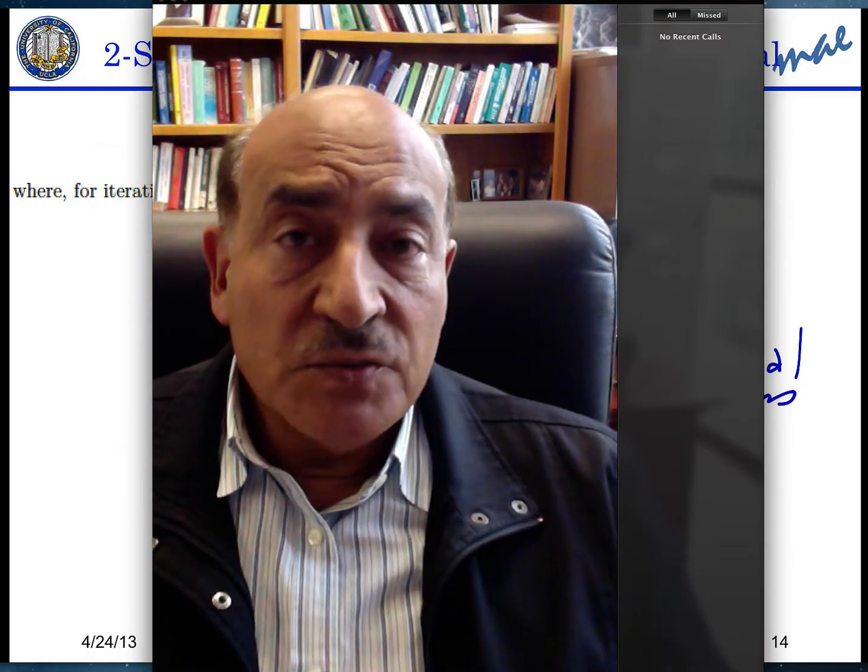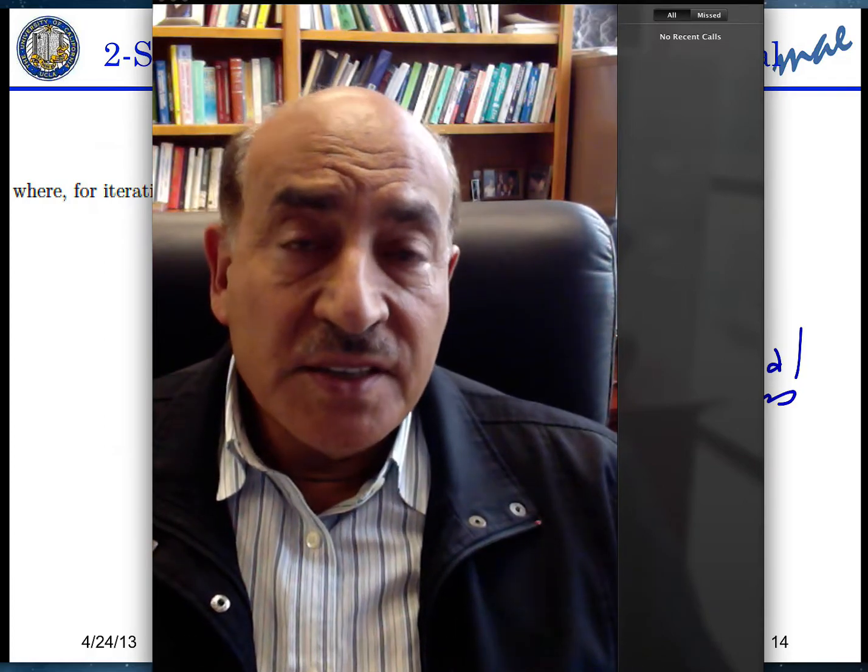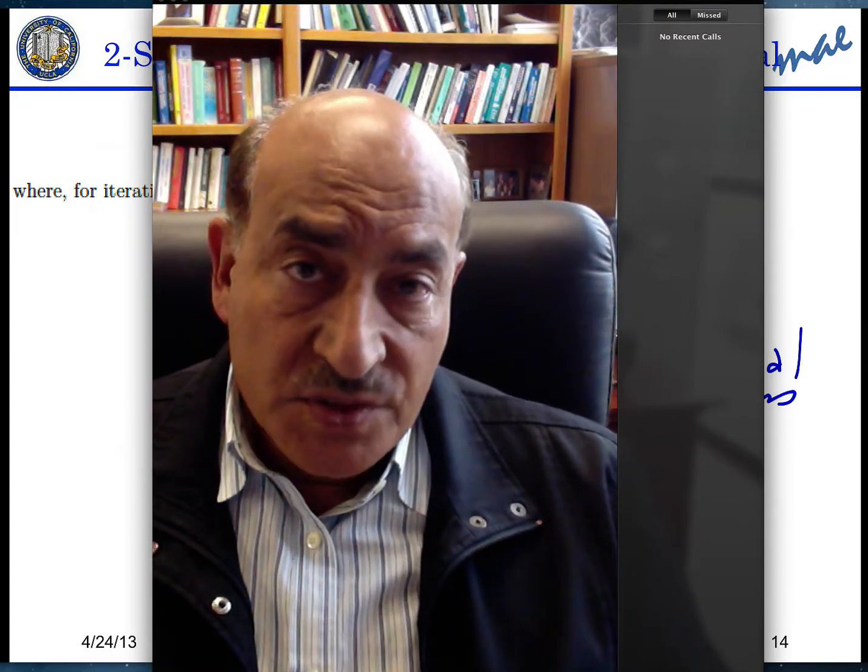Then in this case, what happens if I increase or decrease the temperature? We'll find out, as you will see, that we have something unique here. There will be a unique concentration at which the entire alloy will melt from the solid phase into the liquid phase. And this unique concentration gives the terminology, as we know, called congruent melting. So the melting will be congruent, and exactly at that concentration. So this is one case.